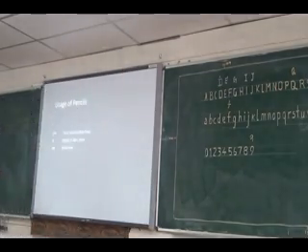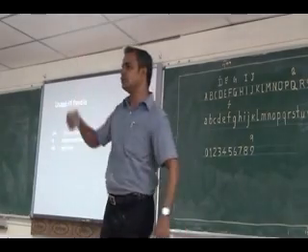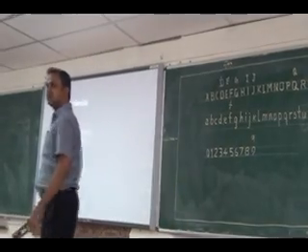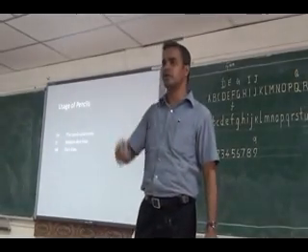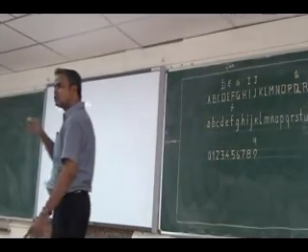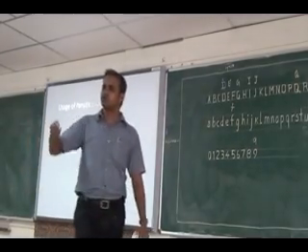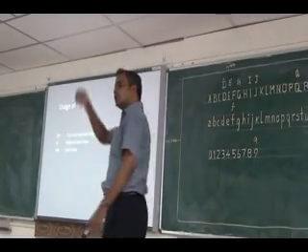You have to use the pencil properly. With the same H pencil, I can give the impression of an HB pencil. If I give more force with an H pencil, it will be darker, still more dark. So if you are going to use a 2H pencil, you have to use it lightly, giving very little pressure while drawing the line.